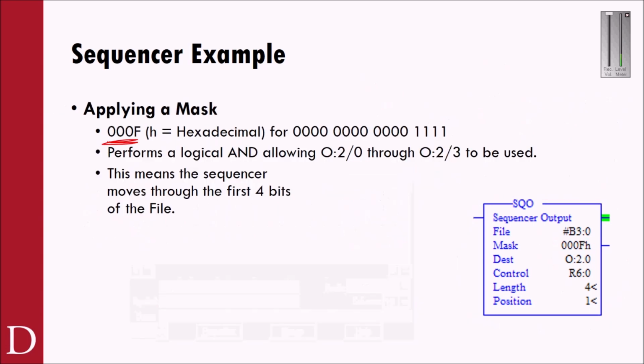So as an example, we saw this, right? We saw that we went from 0, 0, 0, 0, and then we masked it with that F, which is right here. That F there means that 0, 0, 0, 0, 0 are going to AND out. This is an AND gate. They're going to AND out to 0, 0, 0, 0, 0. Why? That was step 1. The reason being is because if I AND out a 0 with a 1, I get a 0.